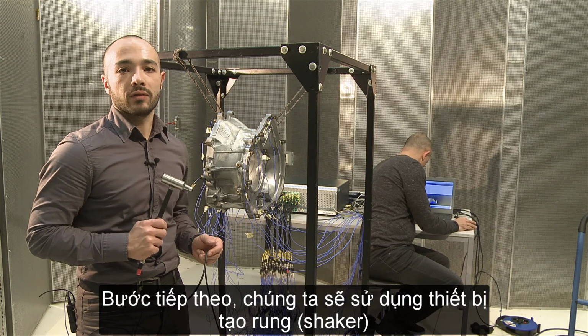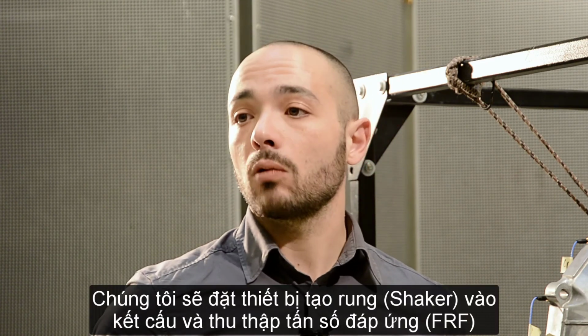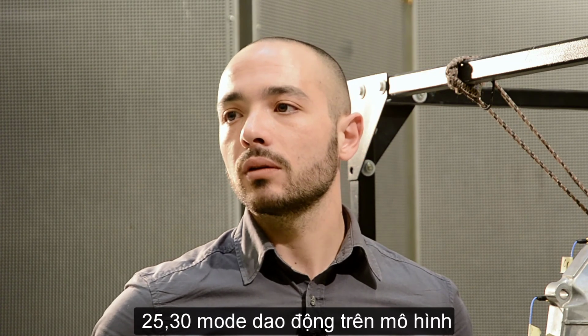So the next step we're going to do after this is we will use a shaker. We will place a shaker on the structure, and then we will acquire FRF in a much wider frequency range to try to identify the flexible modes of the component.